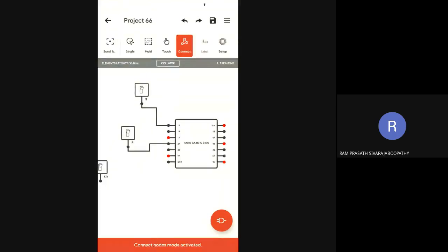It must be the clock, correct? So for the clock I will use a switch here. I am connecting this to 1B as well as 2B. Is this understood by everyone? The first input of the NAND gate, 1A, has S. Similarly, the first input of the second NAND gate has R. The second input of both NAND gates 1 and 2 is the clock. Fine.